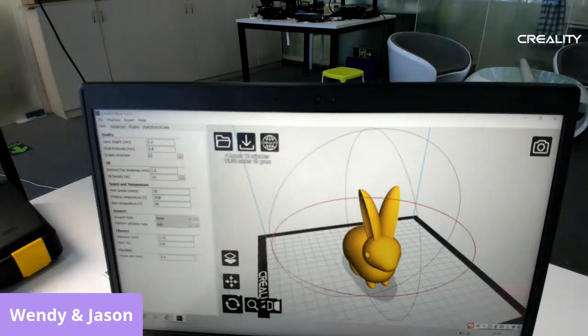All right, so that goes to the filament option. It just shows the diameter of the filament, so 1.75 millimeters. That's just the standard size. The percentage of flow shows 100. I would say it probably controls the flow that goes out of the nozzle. I would say just leave it at 100. It should be fine. And this is the nozzle size of the machine. If you're using a different nozzle, you can change it from there, so the software will know that I'm using a different nozzle. Right. So that's all the basic settings.